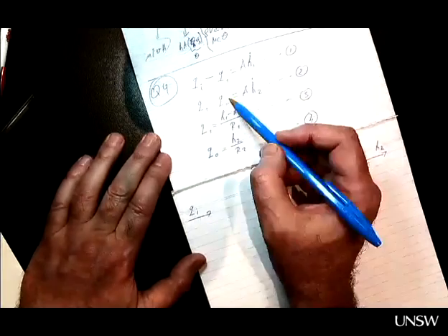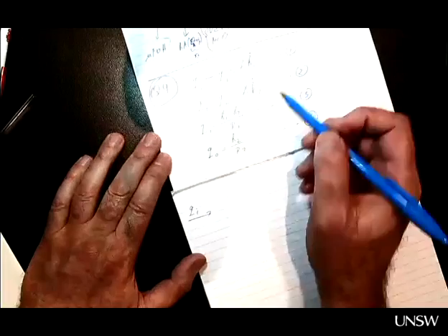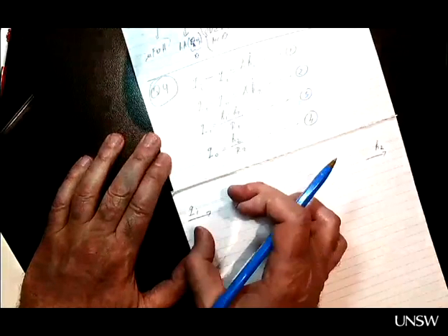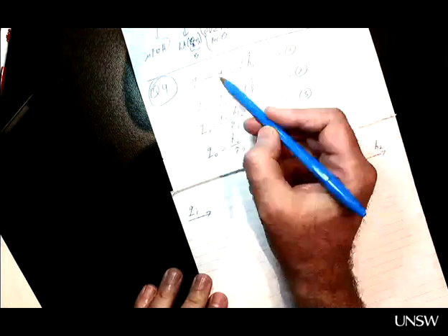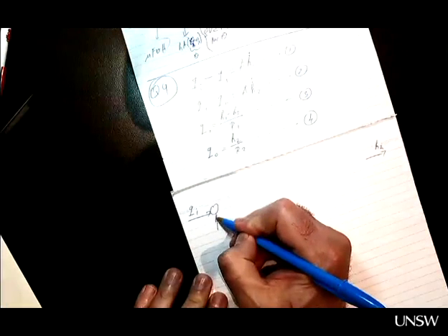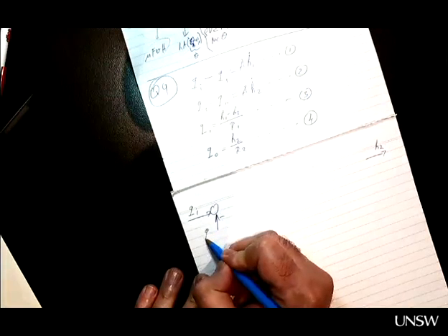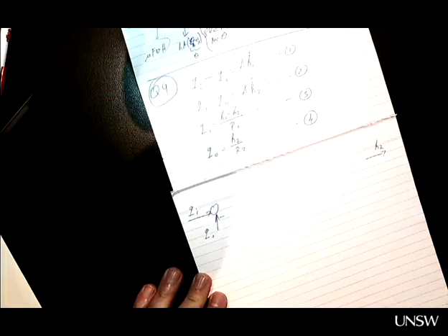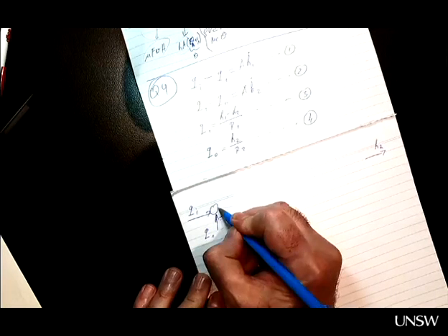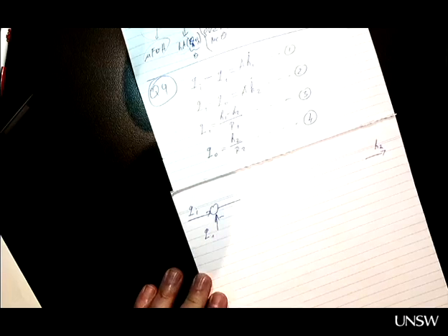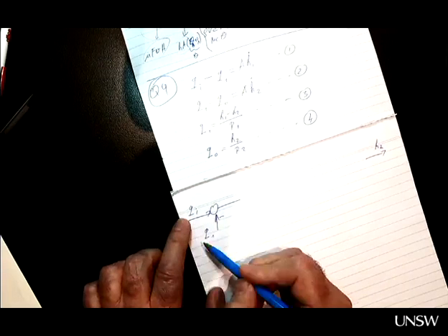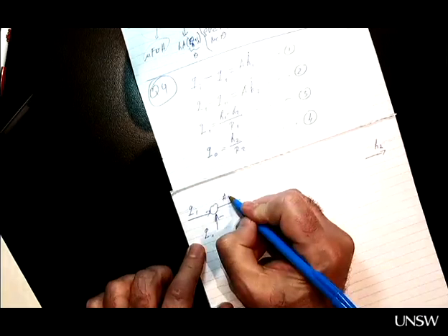So let's create equation 1 here. Let's draw a part of the block diagram that corresponds to equation 1. So we are going to have some sort of summation, Qi minus Q1, equals, I'll just write this here, A H1 dot.